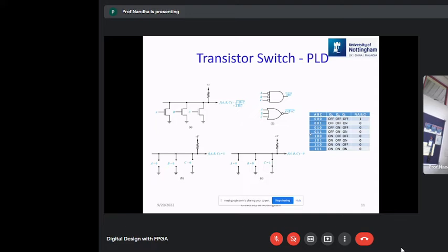So usually when we see the transistor as a switch in the PLD, how does it actually work? When we say that it stores the data, in terms of logic, let us consider, for example, a NOR gate, which is A plus B plus C, the whole bar. How does this actually work? If you see here, there are three NMOS transistors. The gates of these three NMOS transistors are connected to the three inputs A, B, C, while the drains are connected to the power supply, which is VDD.